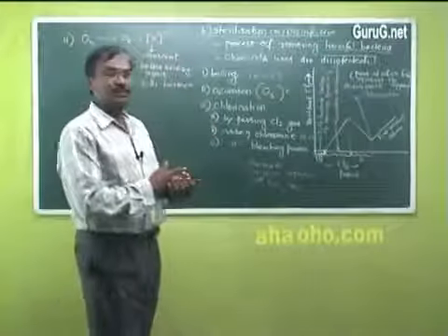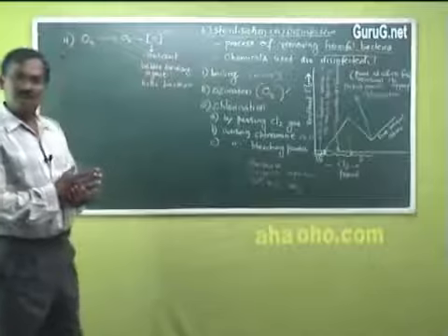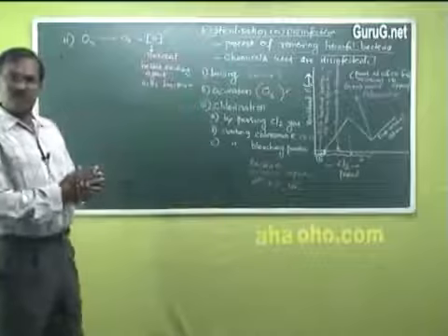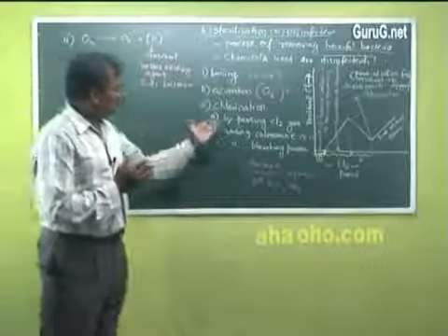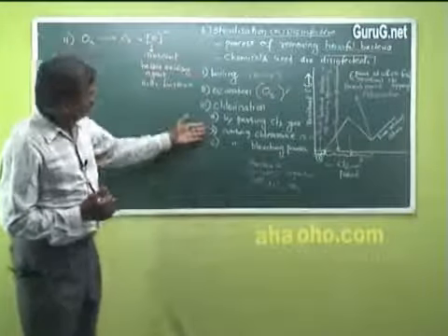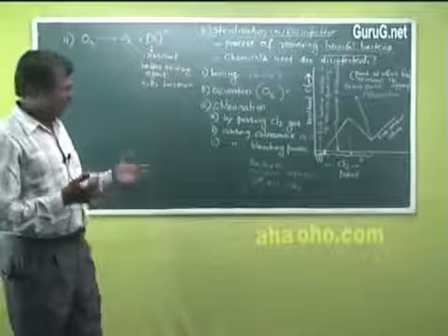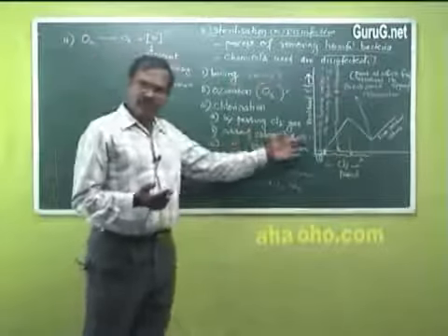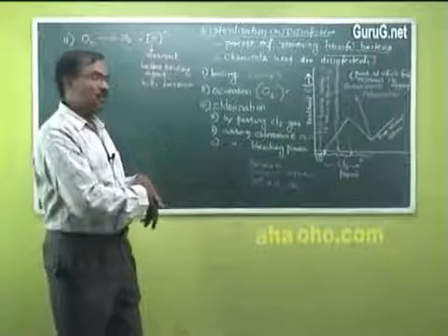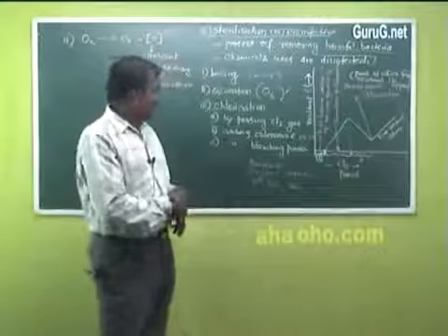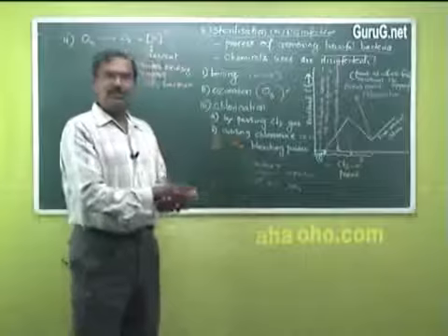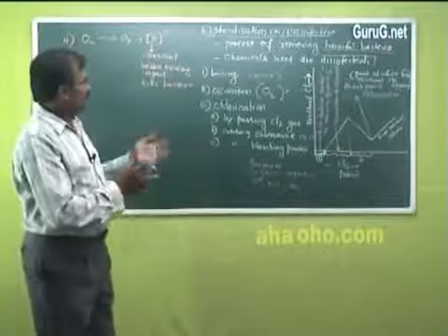So now we are moving to the third one, that is chlorination. Chlorination is carried out by passing chlorine, elemental chlorine gas, or by adding chloramine. Again it is involving chlorine. Chlorine and ammonia are taken in the ratio 2:1, and that mixture is passed through water. And the third one is bleaching powder. We just add bleaching powder into water. Let us see one by one.